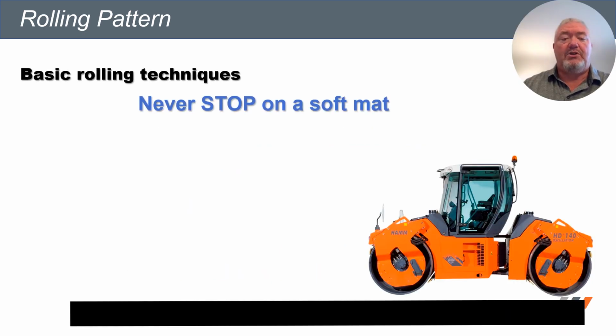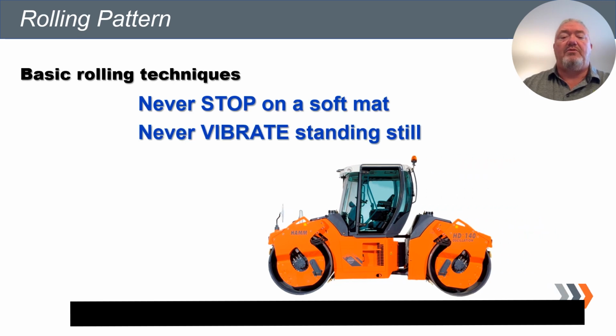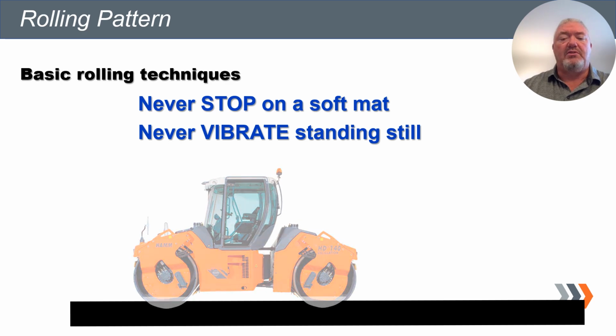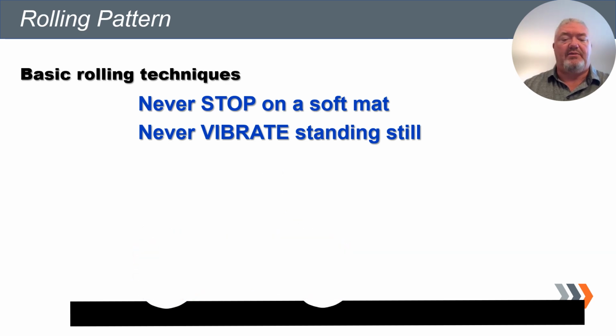So again, never want to stop the roller on a soft mat, whether it's standing still or vibrating, because we're going to put dimples in the mat that we're not going to be able to get out.